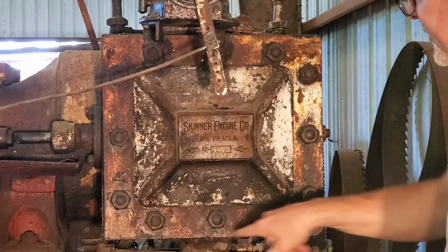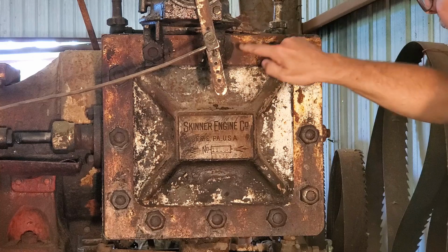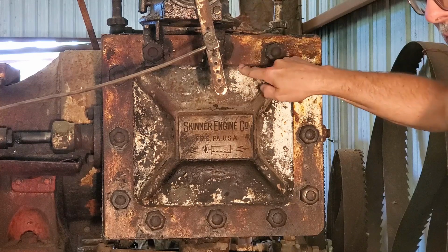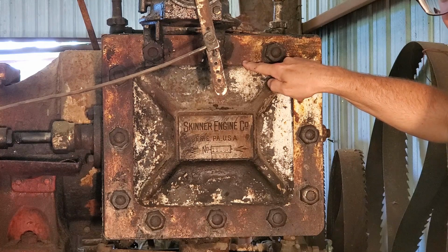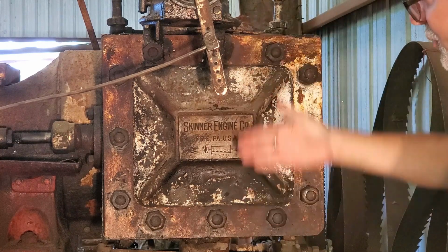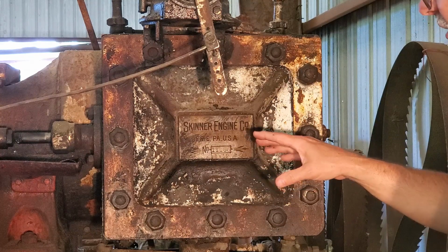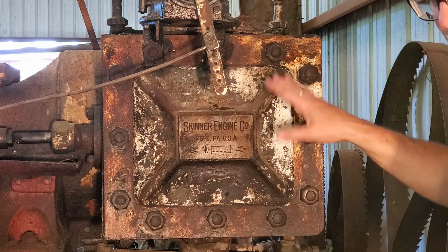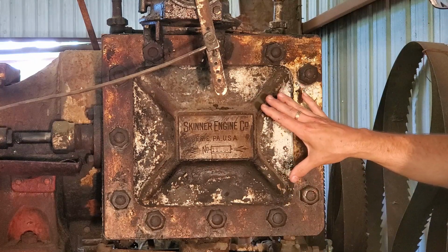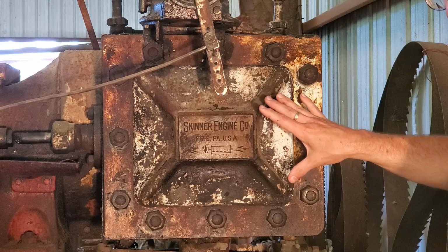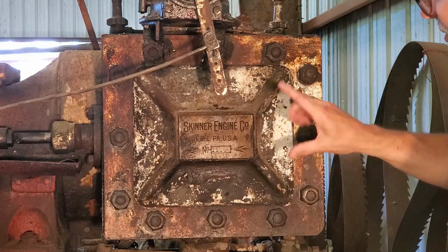So what we're going to do, we're going to take this off, and I'll show you the back side of this steam chest cover, because this is going to go off to Dave Richards, and I'm sure you know him, Old Steam Power Machine Shop. Check him out if you don't. He's agreed to reface this back surface. I have some footage where I took this off and I didn't know what the condition was. I might show you that next, but we're going ahead and pull this off, then I'll give you a good close-up of the surface of this steam chest cover, and also explain how the balance piston works for the slide valve.